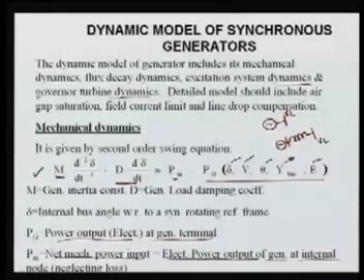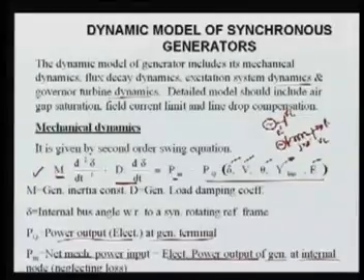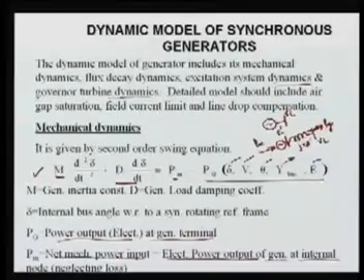Now here we have E prime that is used, sometimes E_F, this is the field excitation. This is nothing but your jX_d prime. So your P_G is here, that is coming out, and your P_M which is coming here, that is input to this, is equal to what is coming at this internal node output.